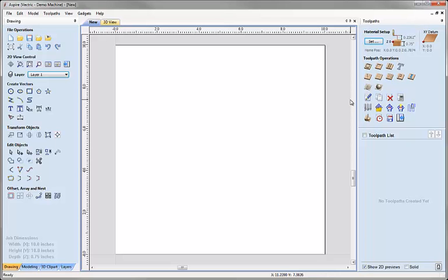Below that, various administrative tools like the ability to edit, copy, delete and recalculate toolpaths. On the next line, access to the tool database, which is where we specify our tool information that we can use in the different toolpaths, and also access to the toolpath templates. Then on the last row here, we have the ability to preview our toolpaths, which allows us to animate them in a virtual piece of material, get an estimate for how long they're going to take to cut, and most importantly, the ability to save the toolpath. That's what we're going to do when we're finally happy with that and we know we're ready to output it and format it in a way that our machine tool will be able to understand it and cut it for us.